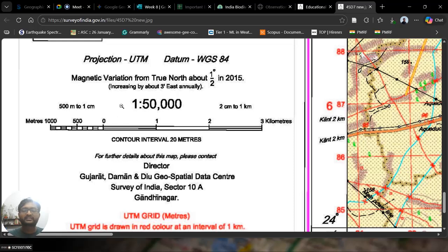And then when this is given to you, to interpret how I identify 1 kilometer in a map, you can use this kind of scale bar. They have converted the scale over here only. So you use this 0 to 1, and you put the similar thing over here, and it will show you the 1 kilometer. Now sometimes we want to measure 1.1 kilometer or 1.2 kilometer. So that's why they are providing the sub-kilometer level accuracy also.